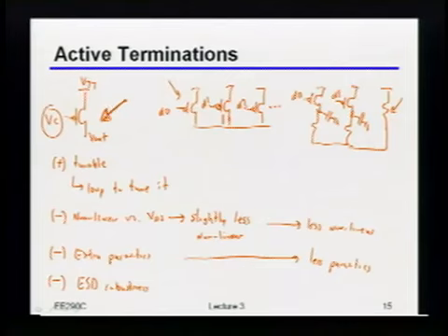Well, if you think about differential signaling, instead of putting 50 ohms to ground, what I can actually do is put 100 ohms in between the two differential lines. Right? So this so-called RAC over here, I can make it, for example, 100 ohms. Okay? Now, you might think, well, why does that really matter?